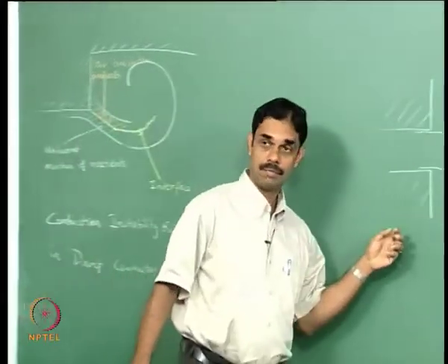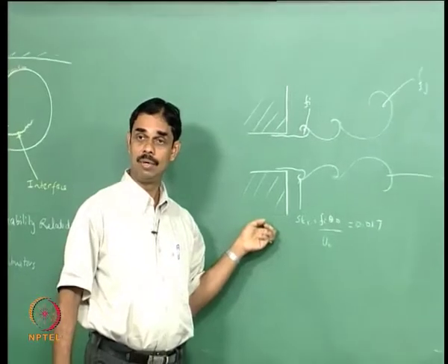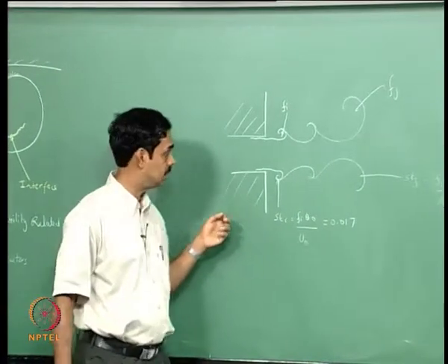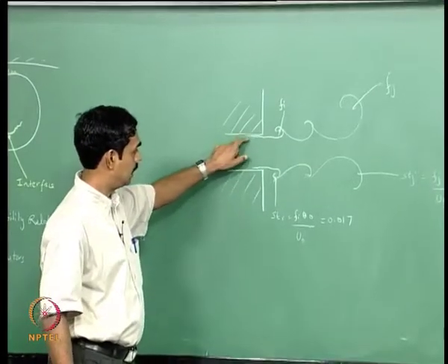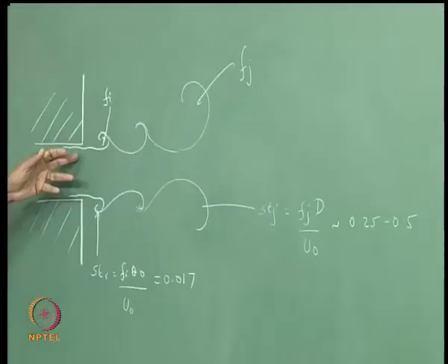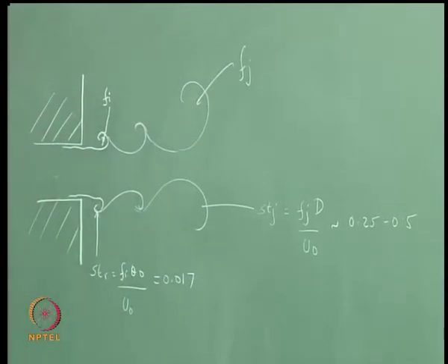And from the basic fluid mechanics of jets, we saw that there are instability waves, and they scale as follows. If the frequency is f_i, where i denotes the initial region, they scale with a Strouhal number based on the momentum thickness and the velocity at the exit.